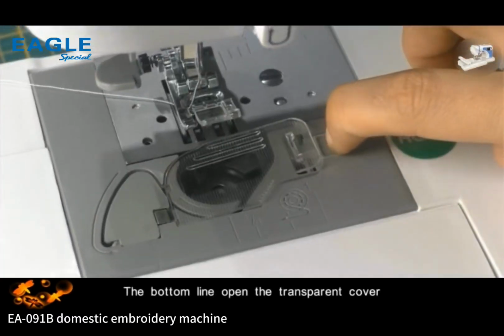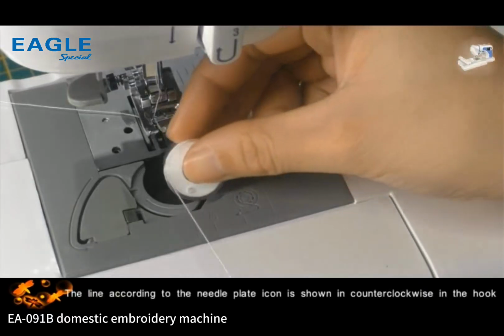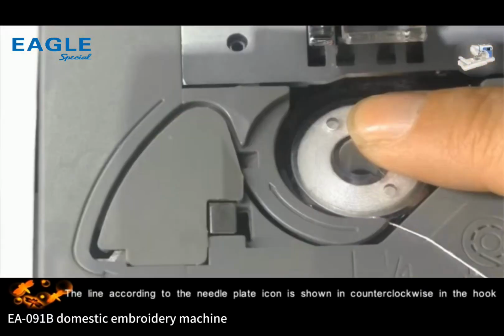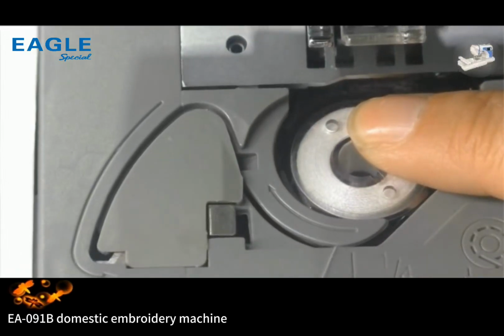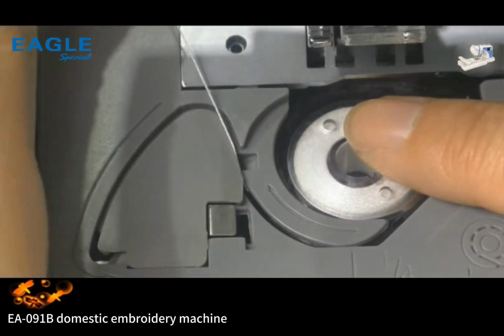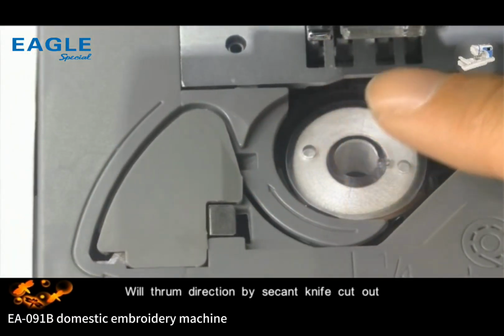For the bottom thread, open the transparent cover. Thread according to the needle plate icon, counterclockwise in the hook. Pass the thread end through the thread cutter and cut it out.